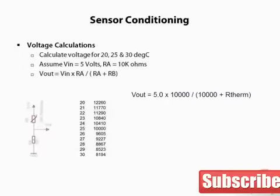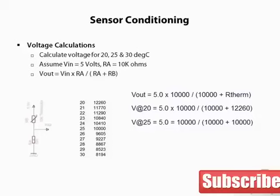Substituting, V out equals 5 volts times 10,000 ohms divided by 10,000 ohms plus our thermistor. So for V at 20, it's 5 times 10,000 divided by 10,000 plus 12,260, and so on for V25 and also for V30.